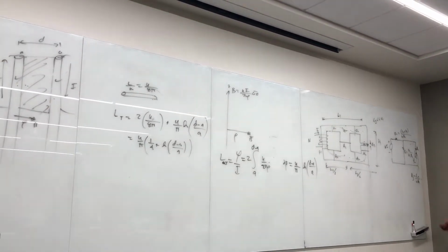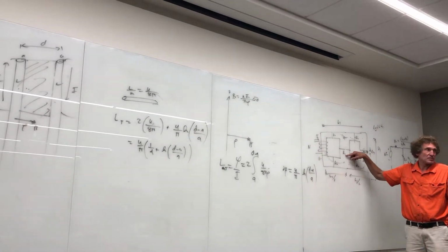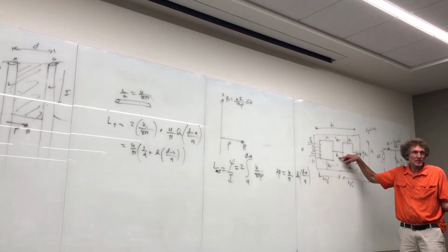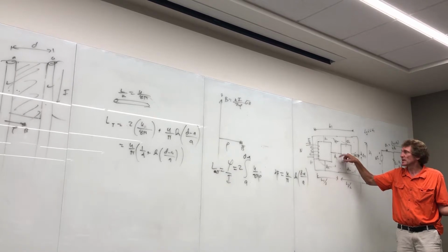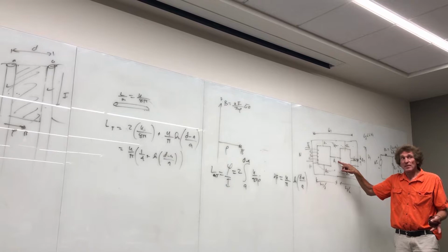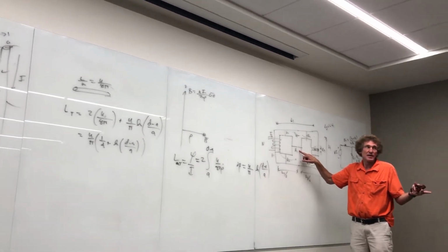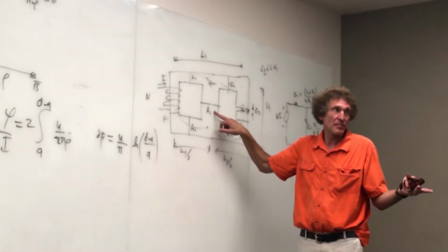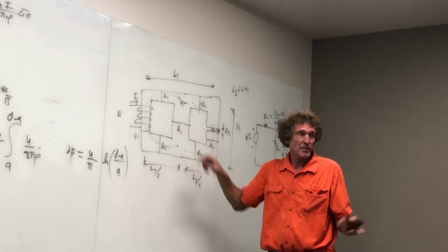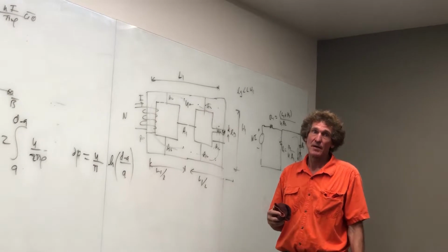But out of curiosity, if I said this middle leg here had a flux of, say, 5 Webers, right? If I wanted the B field there, well, B field is what? That's Webers per meter square. So you take 5 Webers divided by A1. That would be the B field, right? And if I wanted H, well, B is mu H. If you wanted the H field, you take B divided by mu, right? But you can get any of these quantities based on what's given. If you want me to do that problem, I will.